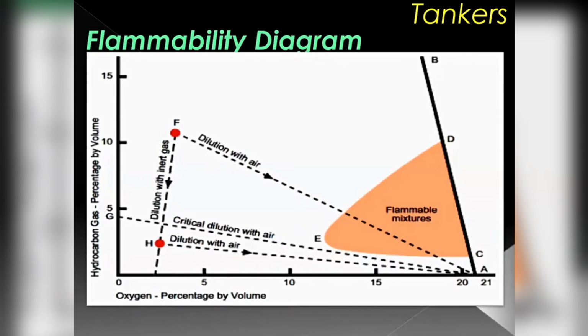You understand what I'm saying? You have already gas freed the tank. That means oxygen percentage is already 21%. You open the tank to check the condition and you find a lot of sludge. That means the tank cleaning was not done properly. So you decide to do the tank cleaning again. What is the right procedure? Anyone from the tanker side? Sir, first we have to bring the tanks again into the inerted condition and then we have to start the tank cleaning. That's right. You have to inert the tank first.